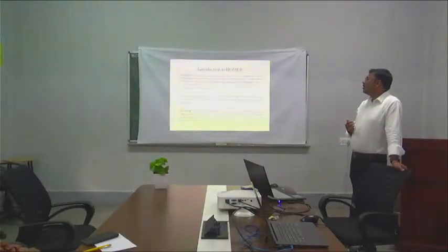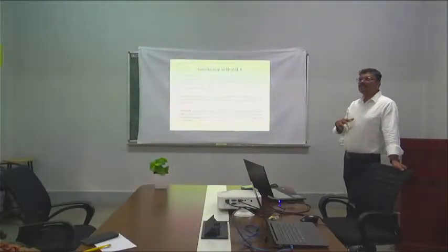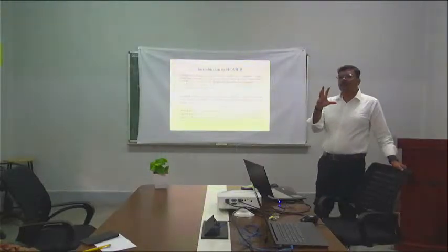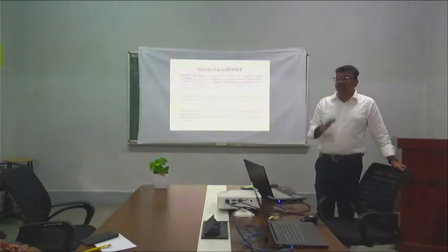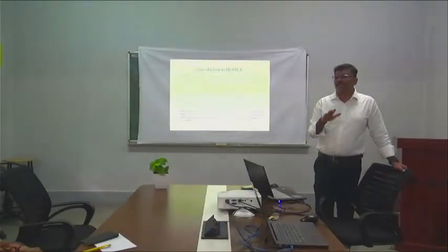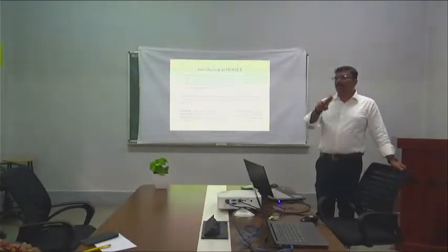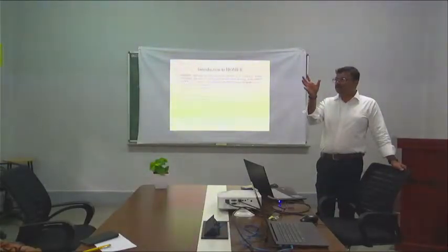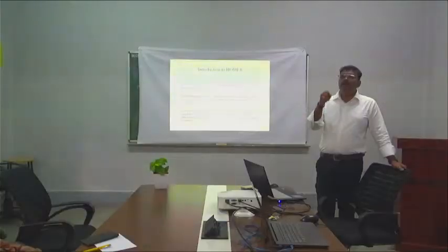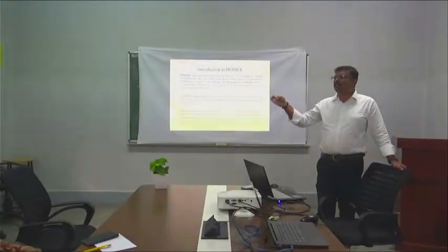Homer allows the modeler to compare many different designs. Sometimes we need to select the optimal design. Wind may not be a feasible solution for this particular location. Maybe solar and biomass is a feasible solution for this particular location. Then what do we have to do? What is the analysis, what are the assessments we do when solar and biomass are active and DG is active?